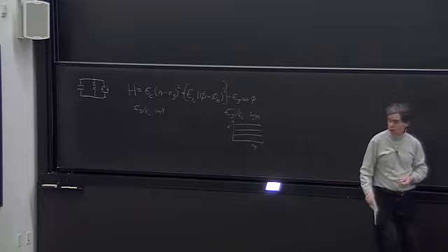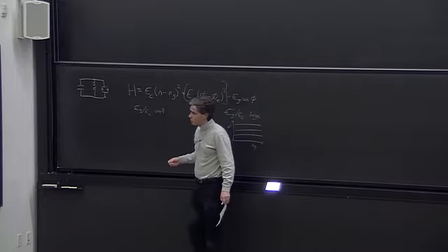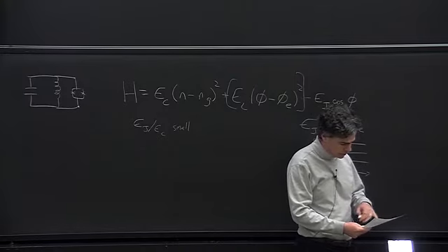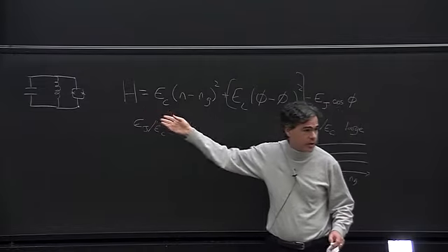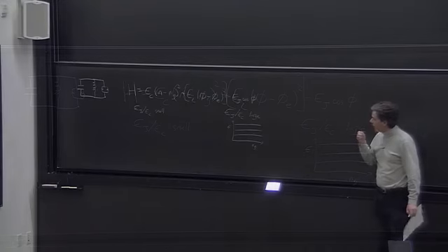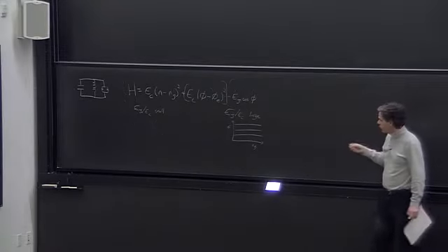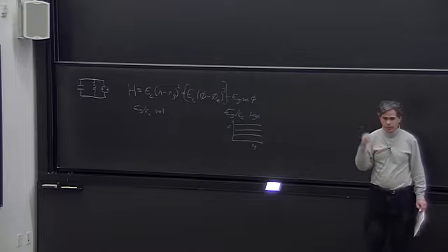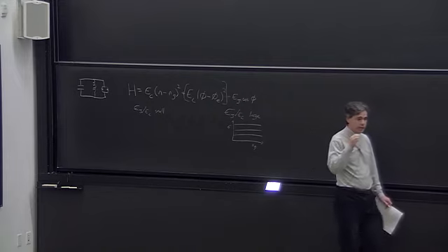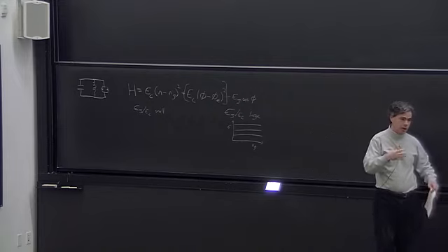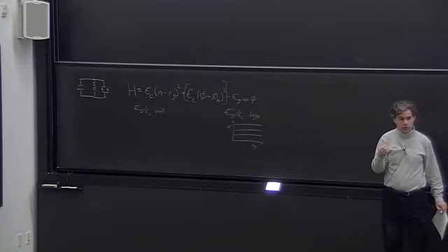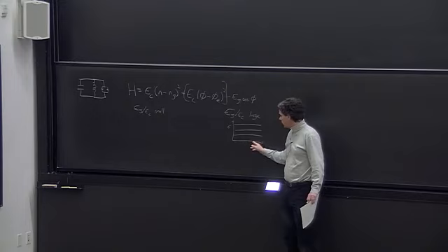So what is Ng? Ng is some parameter in here which just comes out of the exact design of the circuit. It's not an operator, it's a number. And the thing that's going to help decide where we want to be on this diagram is that Ng depends on the ambient charges in the system. So if you have some additional charges sitting nearby, then that can alter Ng.